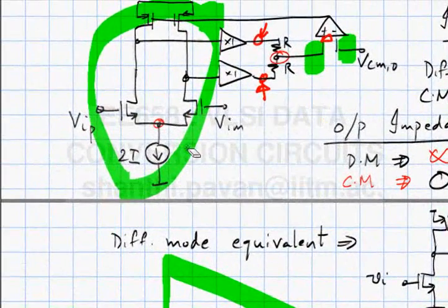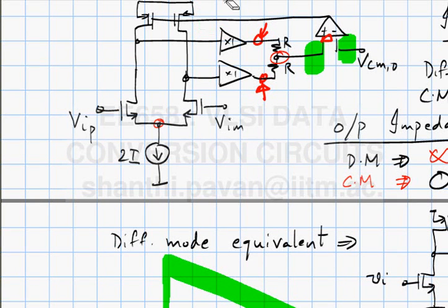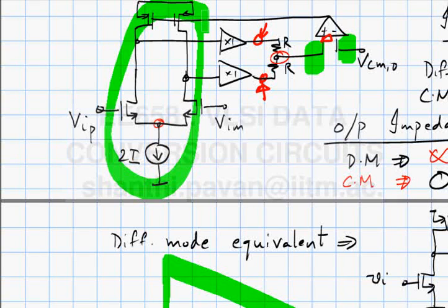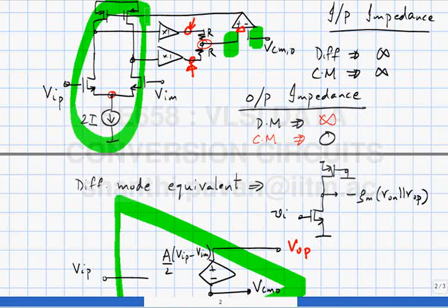And one easy way of converting this: it has a large DC gain, however, the only problem is that the output impedance is very large. You can think of a voltage controlled current source as a voltage controlled voltage source with a very, very large output impedance. This just follows from Norton Thevenin.